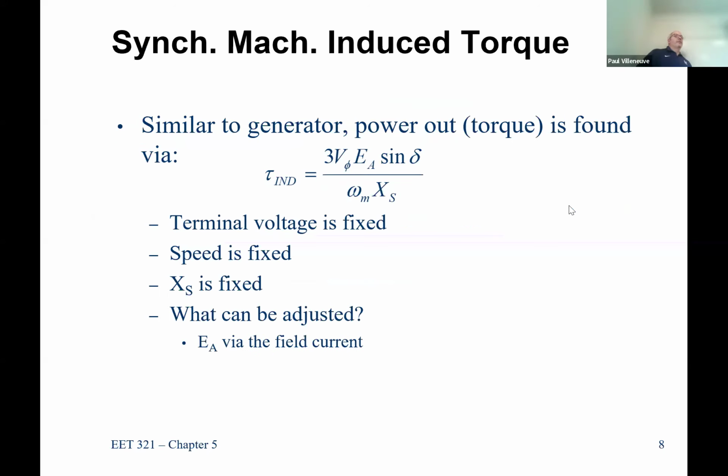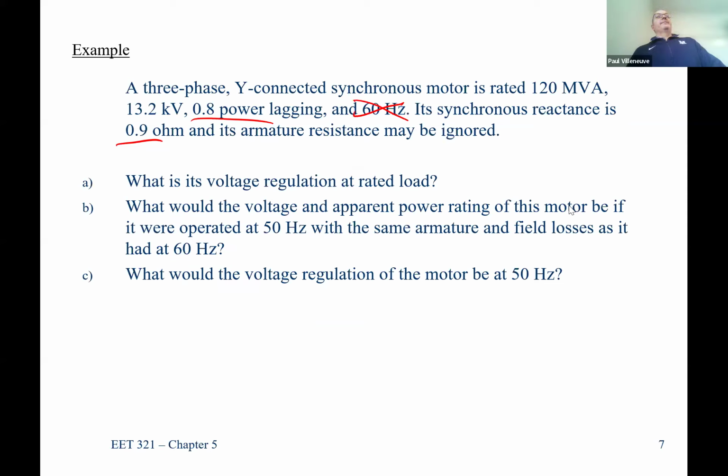All right. Question, Aaron? Well, that's okay. When you have something Y connected like that, it just gives you the voltage. You assume Y goes. In general, in this class and in your career, the voltage is going to be given to you as a line voltage in almost all cases. And what's that? No, you want the phase voltage, because remember, I'm looking for the voltage across here, which is the individual phase. Over here is the line.